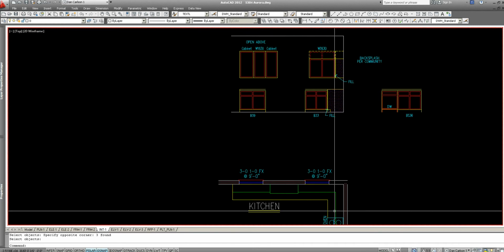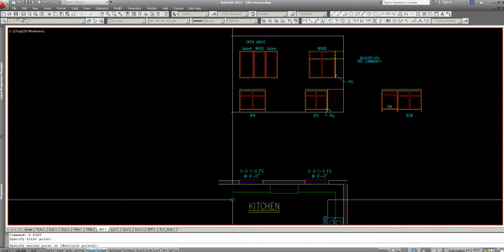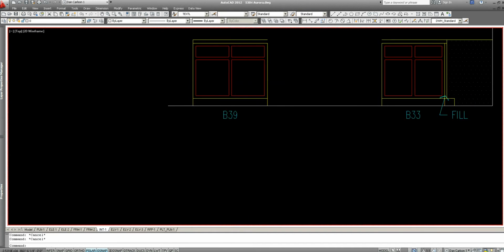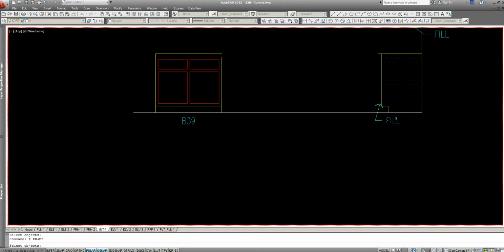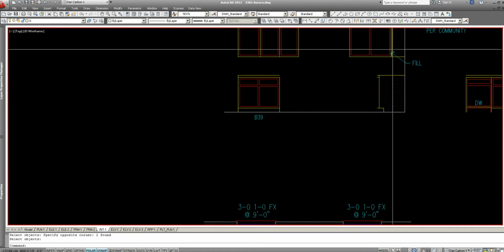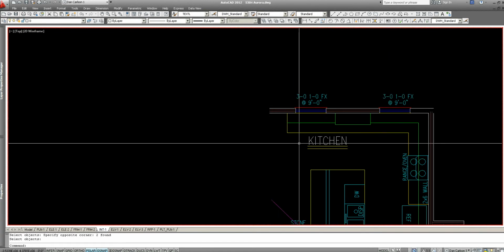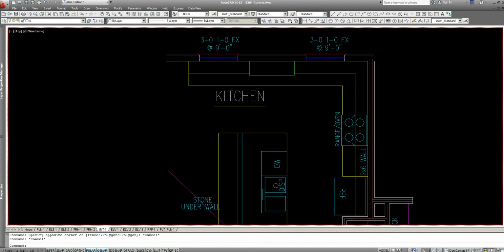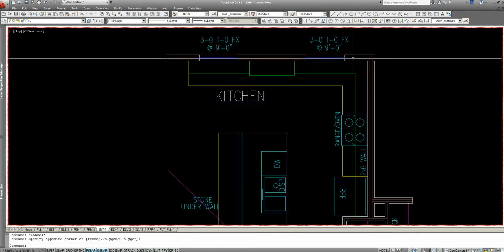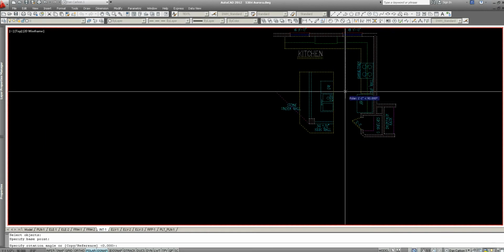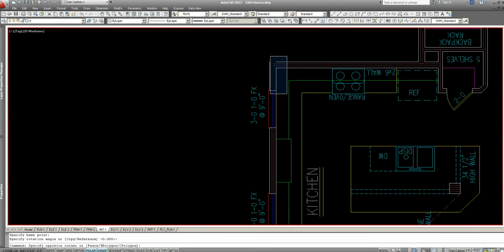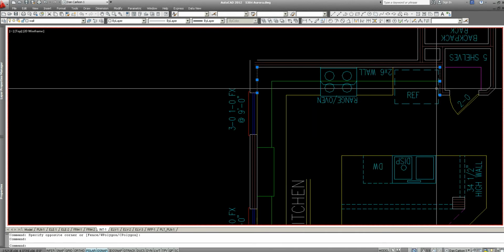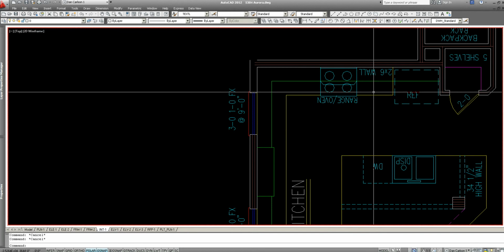So the base cabinets though are just going to be 12 feet, so we can probably just get away with a simple copying. We're not going to need fill. You don't ever need fill like this when one end of your cabinets are open. Now when we do this wall here, because we have a fixed wall here on the left end, here I'll spin it and you'll see what I mean. We have a fixed wall here and we have a fixed wall here. Since the cabinets come in 3-inch increments, we can indeed have fill pieces.